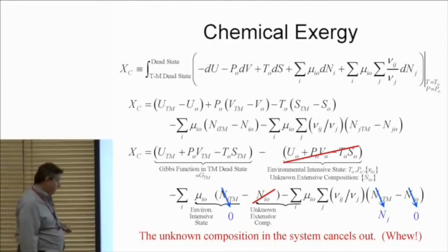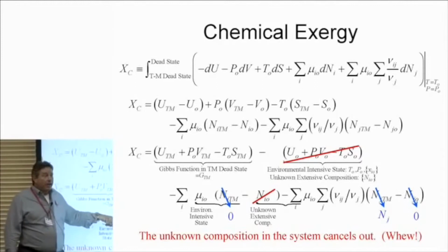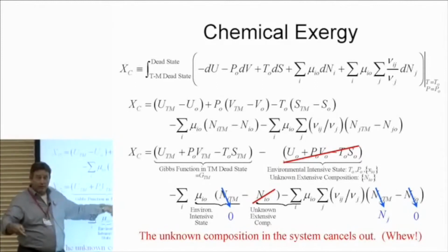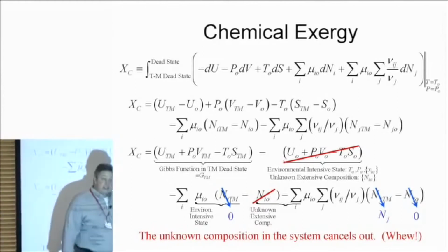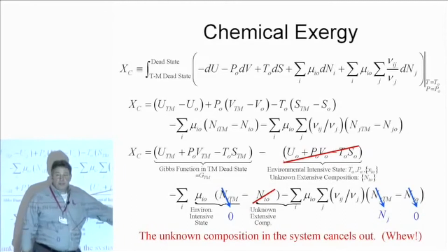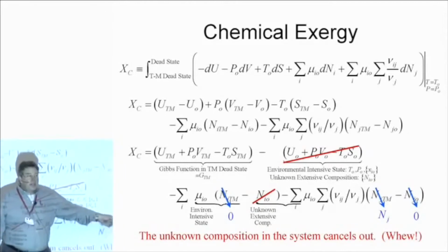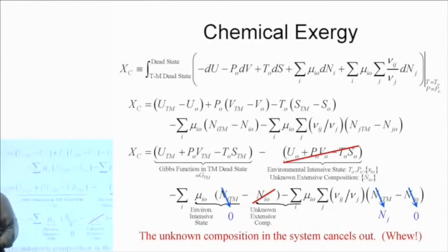Okay, what do we have left? This is the mole numbers of environmental species in the thermomechanical state, but I took all of those and made them all react, even if they react to themselves, so they're all in the J's. So this is just the set of NJs. That's the original composition. It's whatever I've got in my resource. And at the end, all the J's have to have reacted. They can't be around anymore because they cannot be released to the environment.